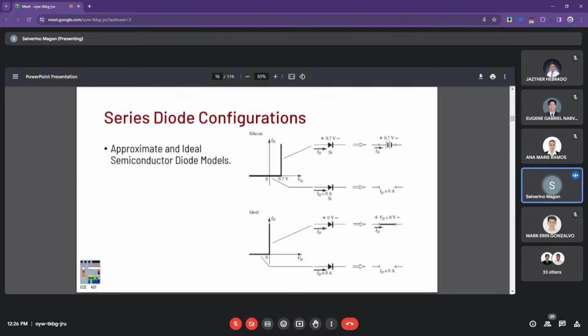So here is a sample approximation of how ideal diode models can be represented by the following. Now, for ideal silicon, you don't have the ohmic region considered in your equations. Then you have just a simple voltage source at 0.7, right? That's in the on condition. In the off condition, this is just merely an off switch. Again, that's for silicon, for both cases.